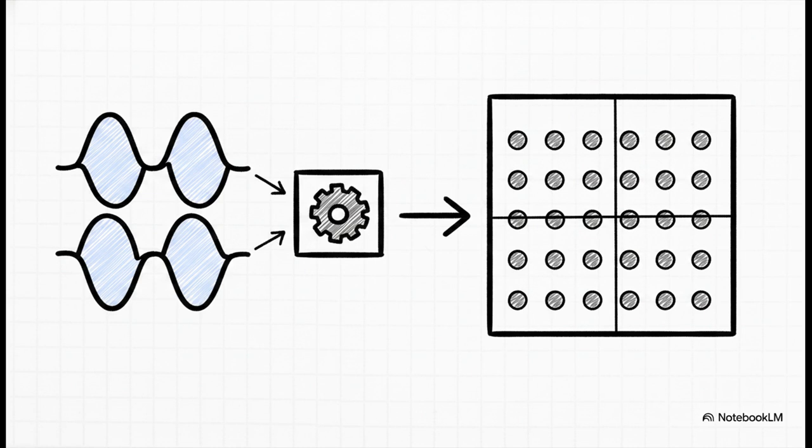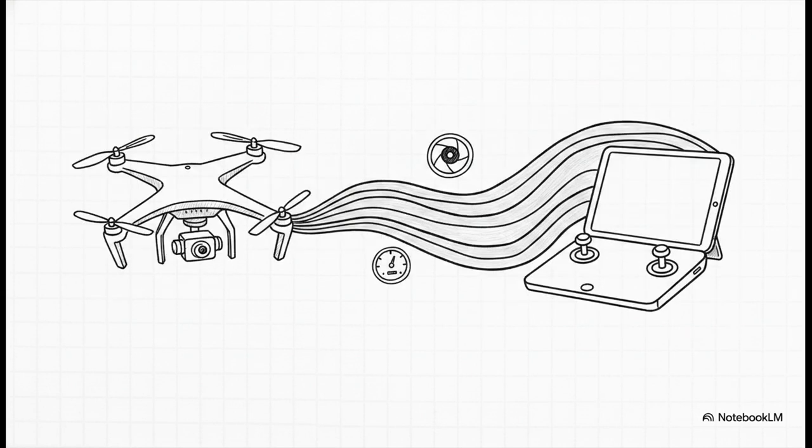By tweaking the amplitude of both carriers at the exact same time, QAM lets us pack way more bits into every single symbol. We're talking a massive upgrade from simple analog pulses to dense digital constellations like 16 QAM or 64 QAM. It is incredibly efficient. And that leap in efficiency, that's what changed the entire game. Standard AM could literally never handle a video feed, but QAM completely solves that low data rate bottleneck.